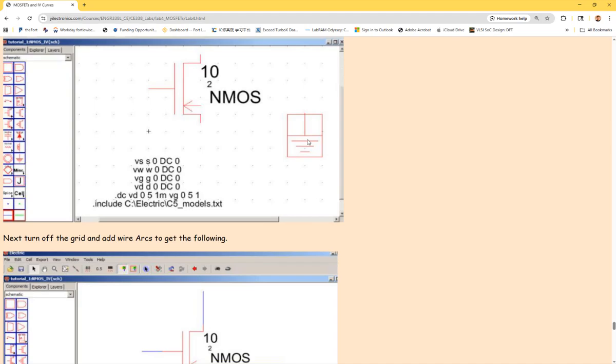So you don't have to export VDD and grounds. Like you build a little circuit, and you build another circuit to wrap it, and you build another layer to wrap it, right? So you export all the pins in order to make them visible at the upper hierarchy, right? But for global power sources or symbols, you don't need to export them. So VDDs are always VDDs. You place the VDD symbol at the bottom layer, and you can directly use it at the top layer. They are automatically exported to the top. Same for ground. So you can directly use VDD or ground. They are always universal global pins. Any questions on this?